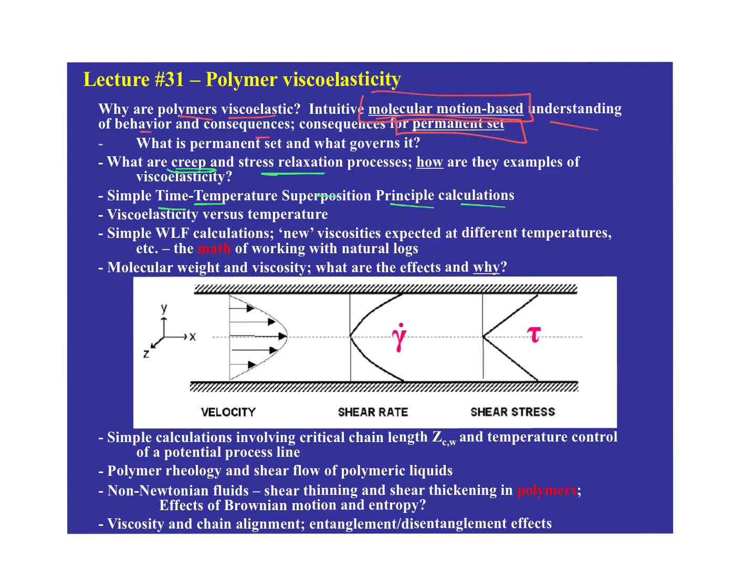And you need to understand how viscoelasticity versus temperature behaves, which again relates to molecular motion, which again relates to how quickly chains can move, and be able to understand as we go up and down in temperature what happens to viscoelasticity. Again, you understand a lot of this background issue now, and so these things should be familiar to you.